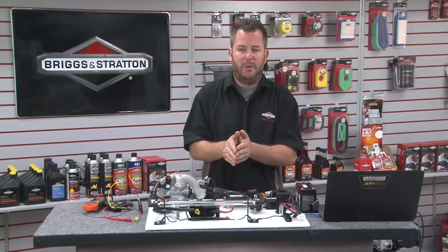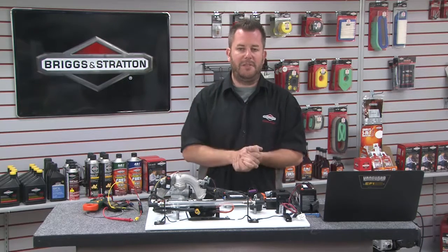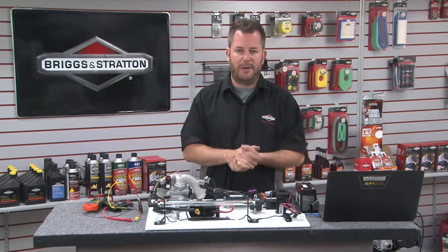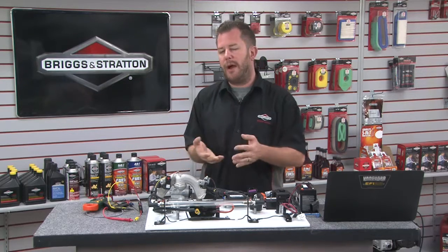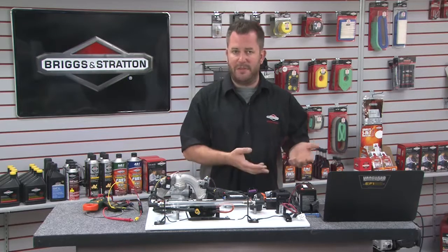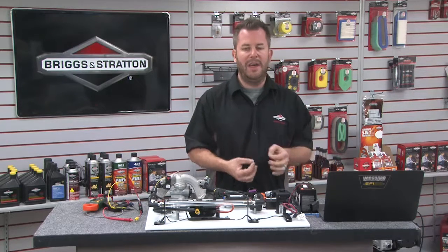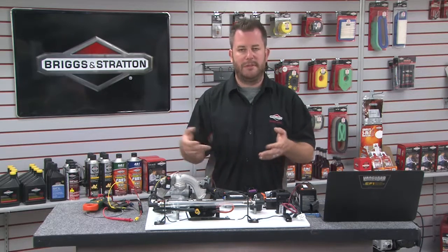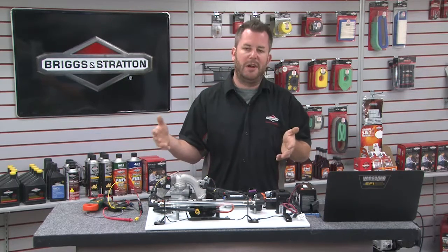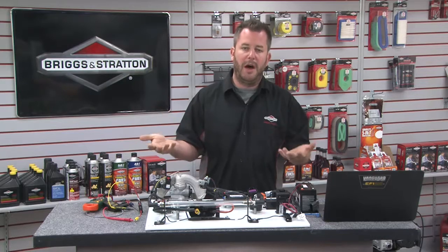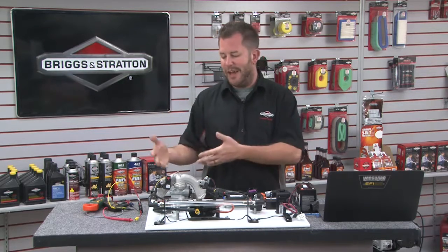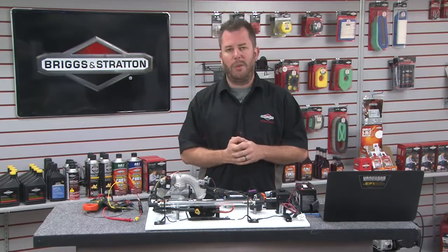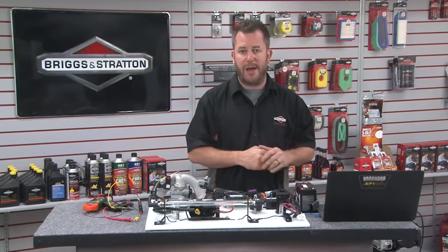So it basically will mirror exactly what the head temperature is telling us, and it gives us another thermal input here for that circuit to run. So this is one code that probably won't produce much of a performance loss, or at least a noticeable one, because it has something else of nearly equal value to fall back on. There's maybe only about 30 degrees difference between the two on a normally functioning engine, so it's not a giant impact to performance. So now let's take a look at how we would troubleshoot this using the laptop software.